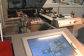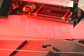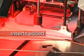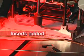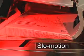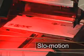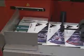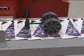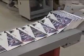If there is more than one insert sheet, they are now fed, cut, and folded in the same manner. The inserts are now inserted into the folding station. The envelope sheet, which is now on the bottom of the set, is scored and folded around the inserts, and pressure is applied to seal the envelope. The completed piece is then sent to the shingling conveyor. This process is the same for A3, A4, 8.5 inch by 11 inch, or 11 by 17 inch sheets, with the exception of the cutting step.